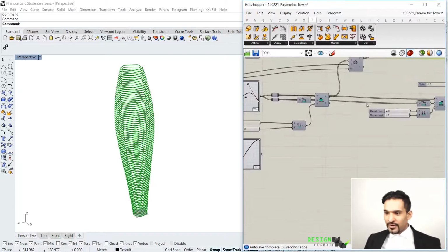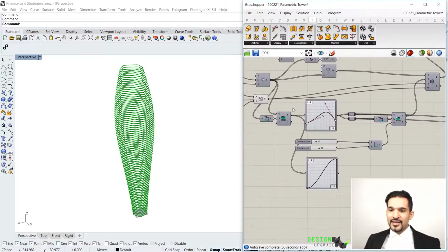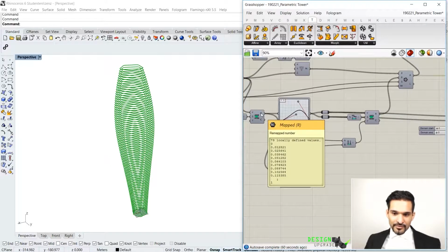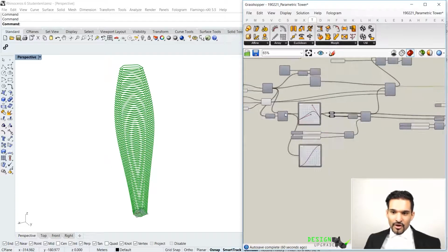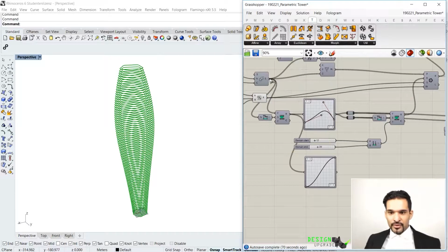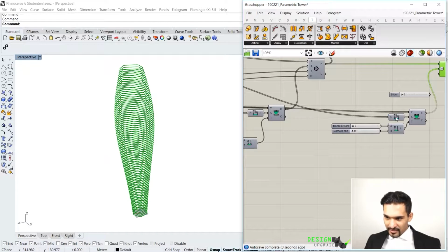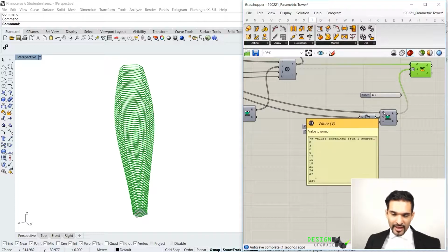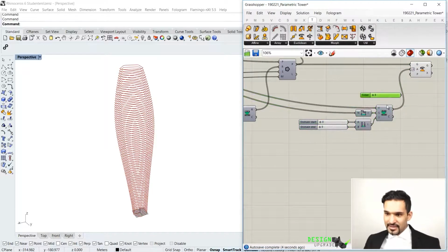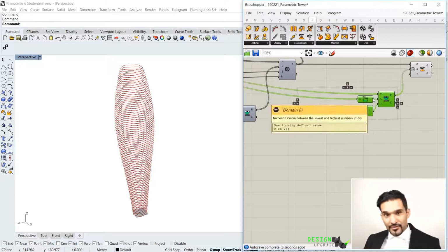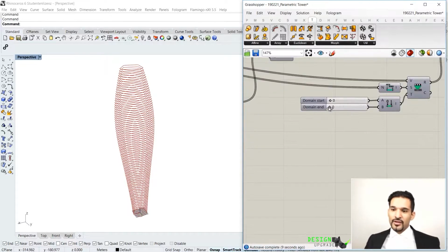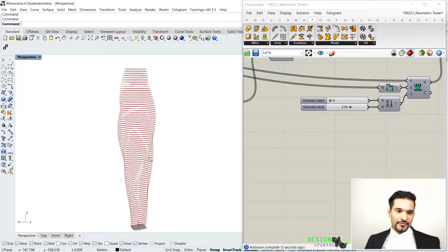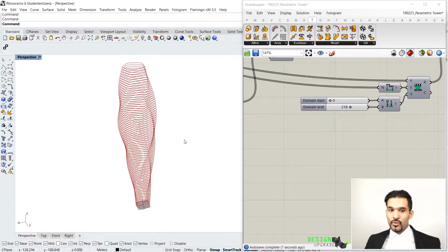And that is simply or easily done by taking in the inputs that we had before here, right? So we can just take in maybe the R input from our first remap function, yeah? Or we could just take in the series component and put this into our domain bounds, and our series goes also in our V for values. Now what we have done here is simply saying that this is the first list that we had, which is a linear function. And now the rotation is also being linear, as you can see, because that's something maybe more likely for you to understand or to work with.